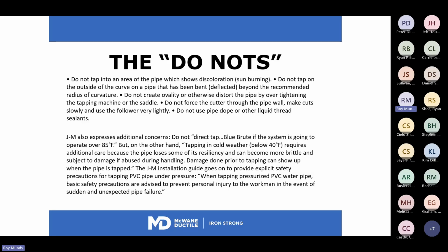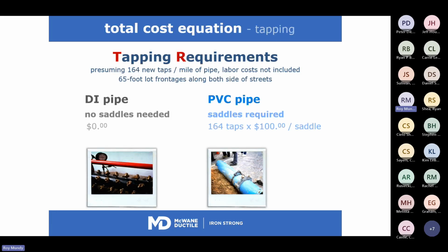So effectively, Tom will not tap PVC pipe without using a tapping saddle as a factor of safety.